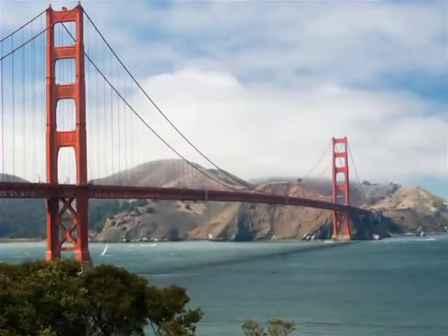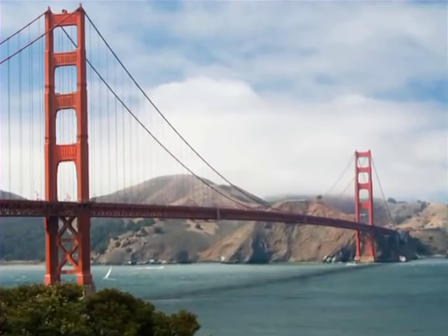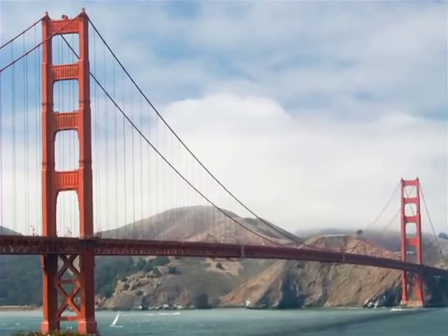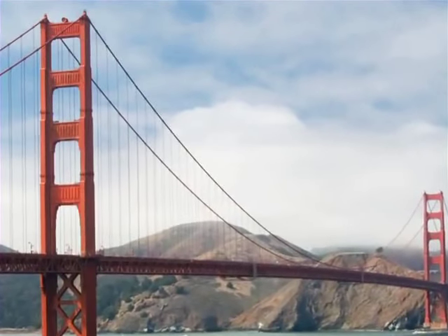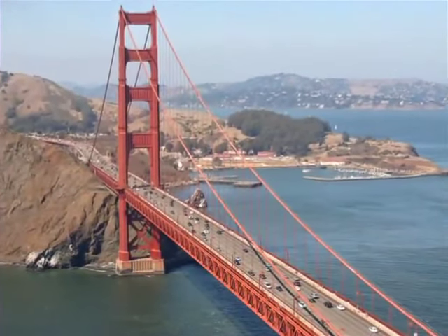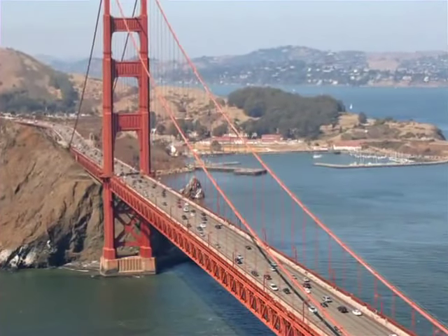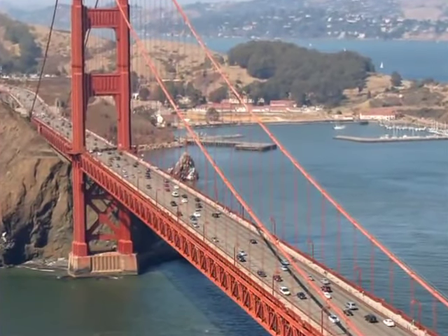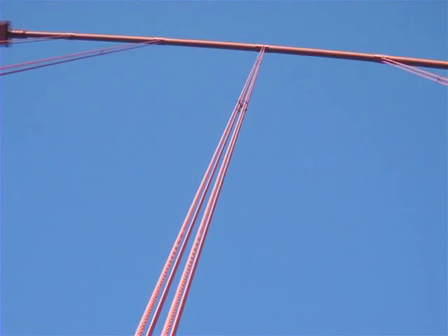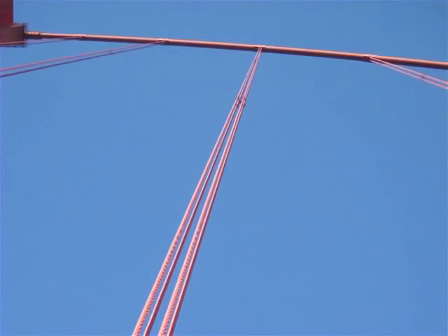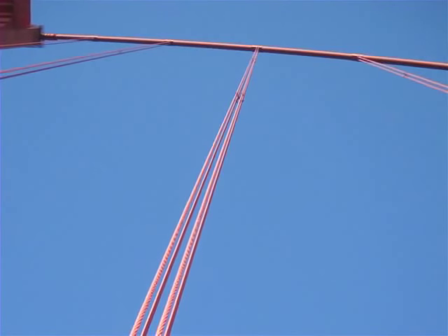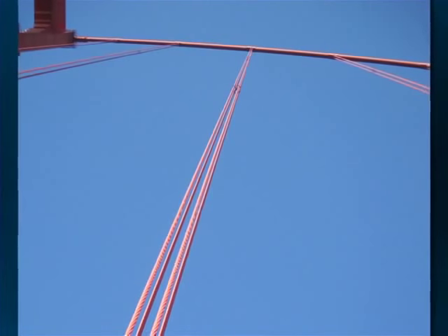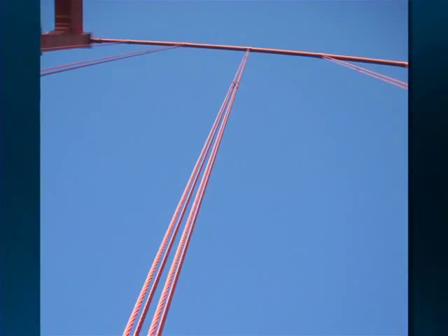For example, here's the beautiful Golden Gate Bridge. And if we look closely at the bridge, we'll see these vertical cables, the suspenders that I referred to back in Lecture 1, are excellent examples of tension members. They're called suspenders because they suspend the bridge deck from the main cable, so they're clearly loaded in tension. The Golden Gate Bridge has 500 such suspenders, arranged in bundles of 4, as you see, and spaced at 50-foot intervals along the entire length of the bridge. The suspenders look tiny in this photo, but in fact, each one is a bit over 2.5 inches in diameter and can carry about 500,000 pounds of internal force.